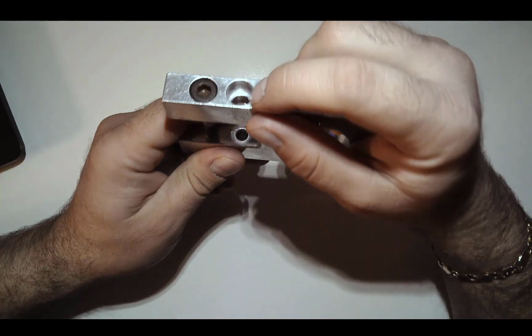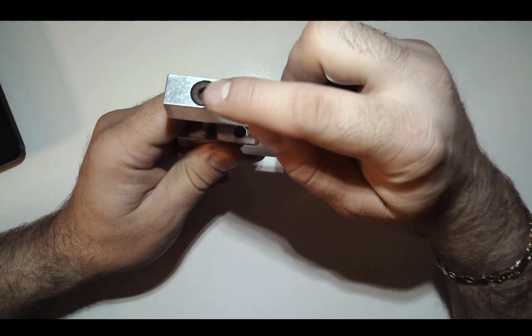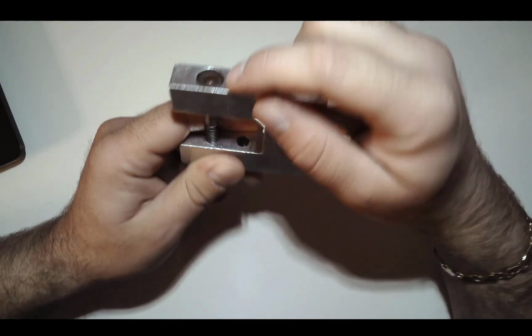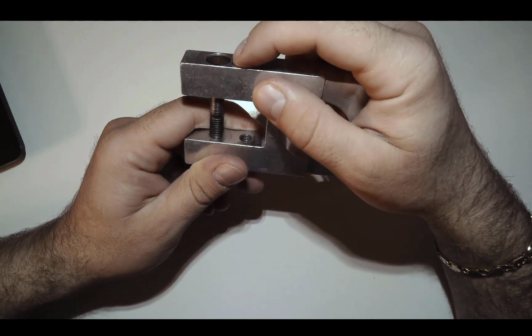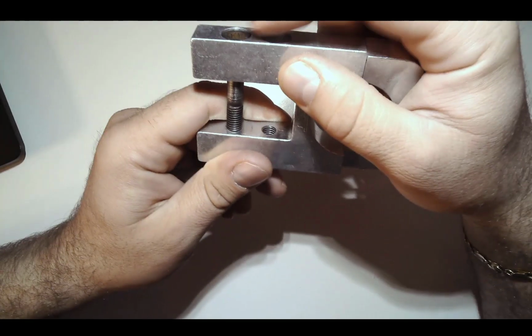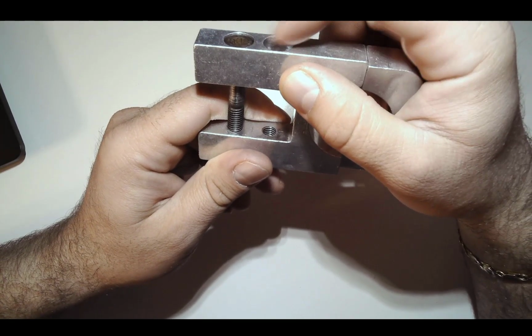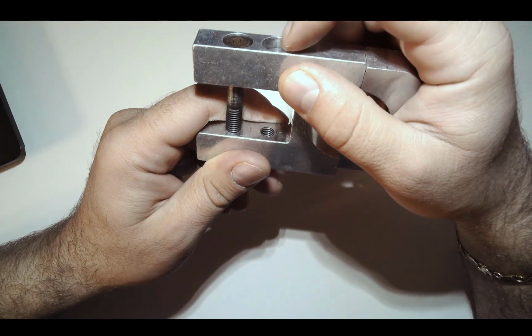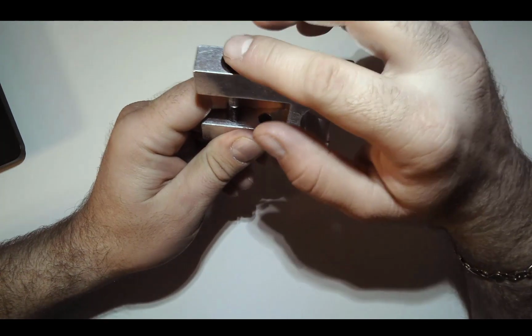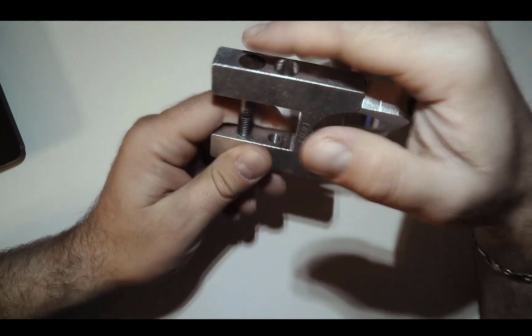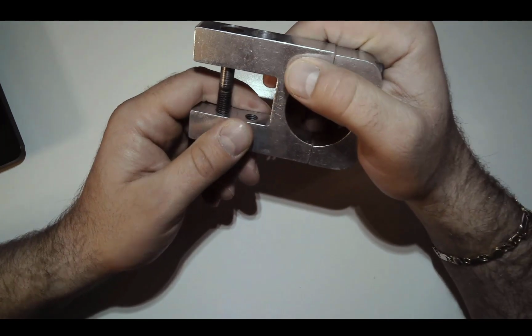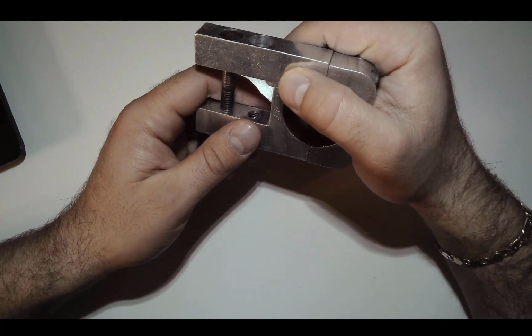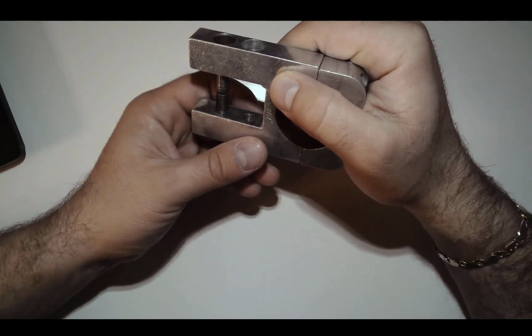and tighten or loosen it. This counterbore is suited to allow the socket-headed cap screw to be tightened up in the assembly, and you can see that the cap screw is just subsurface of this side of the bracket. That allows the head to be below the surface so that it doesn't interfere with other components in the assembly, and it provides a nice aesthetic to this component.